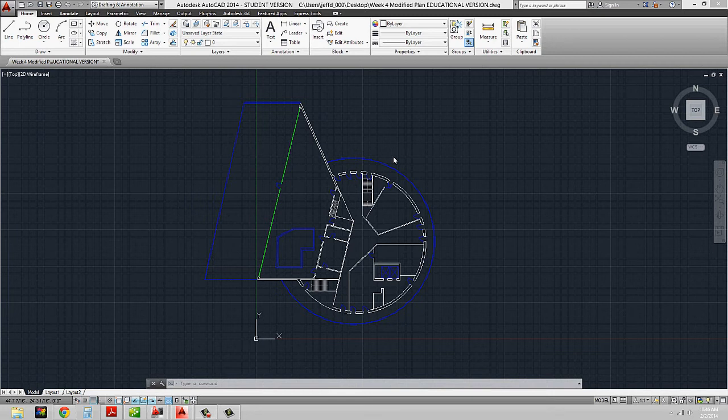Blocks are also really useful if you have multiples of one object. For example, if you have doors or windows, oftentimes you'll make blocks out of those, and you can just use them over and over again. Once a block is created and copied, if you need to change it, you can reference the block and make changes, and those changes will reflect throughout the whole drawing. Blocks can either be defined within the drawing, exported from a drawing, or, as a separate file, inserted into the current file as a block.